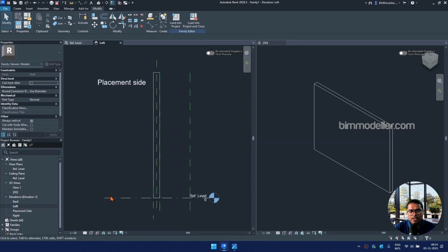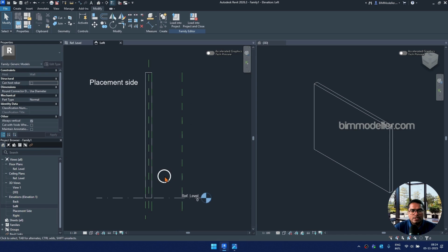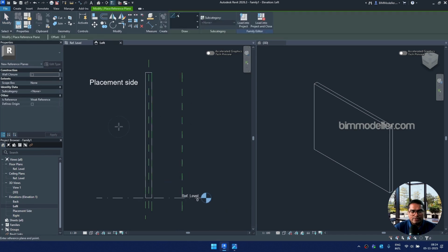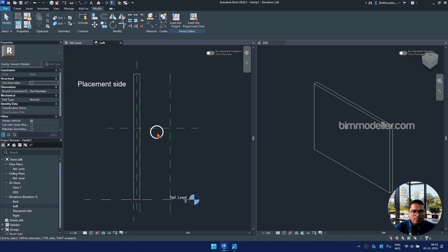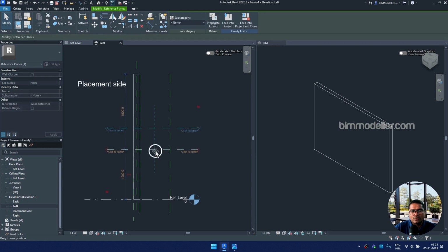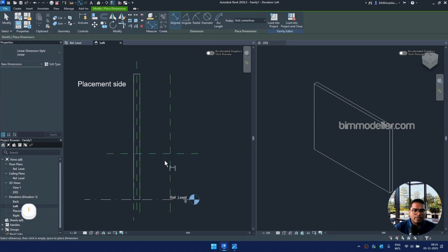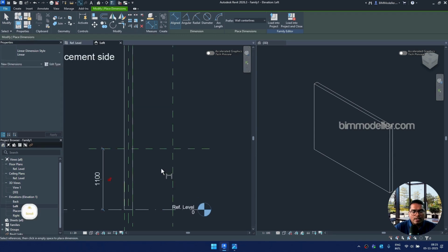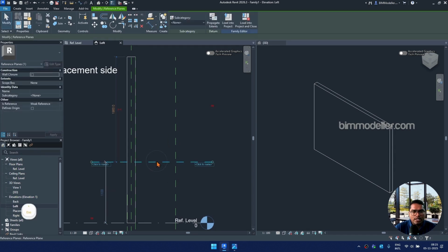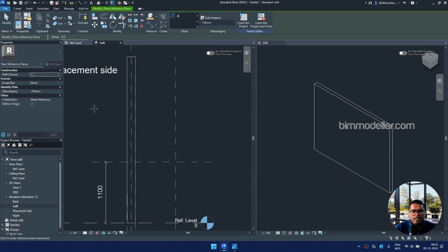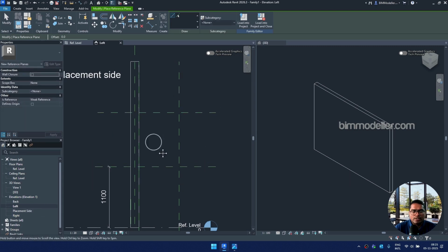I have taken the wall-based family, generic family template, and I'm going to create this as basis like this. So the table height is going to change, so we can have the height parameter from here. And from here we will have a supports and we will have a tabletop. So we have to create similar, and we will have our top side like this.